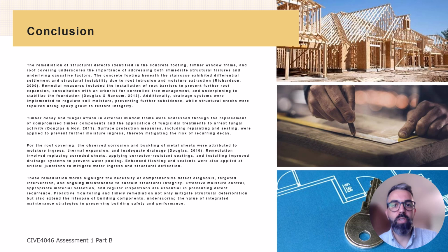For the timber window frame, timber decay and fungal attack were identified, with proposed measures involving the replacement of compromised timber components and the application of a fungicidal treatment along with surface protection through repainting and sealing.